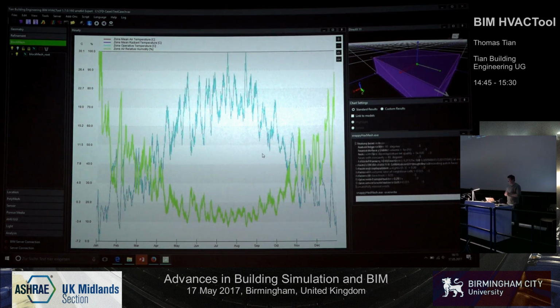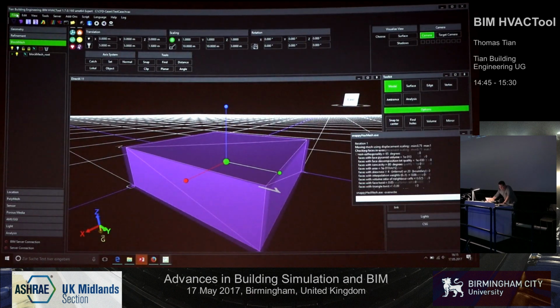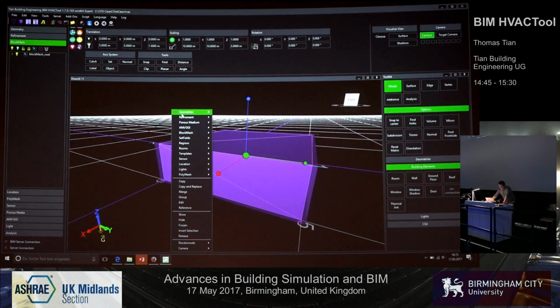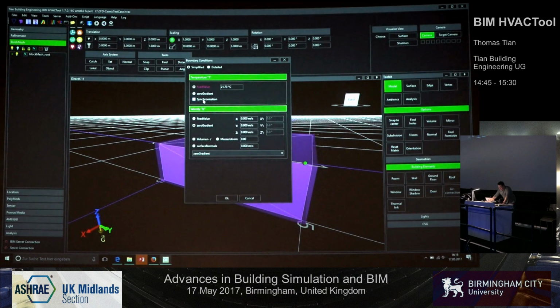But what you can do is, you close it. So, snappyHexMesh is done. But for the boundary conditions for OpenFOAM, you go here and you can say yes, and it will update my temperature or my heat flux. So if I choose winter time, I only choose like October or November, it will update my whole building for OpenFOAM and push it to OpenFOAM, and then I can see what happened with my heating or with my building. If I choose summertime, it will update my boundary conditions for summertime.